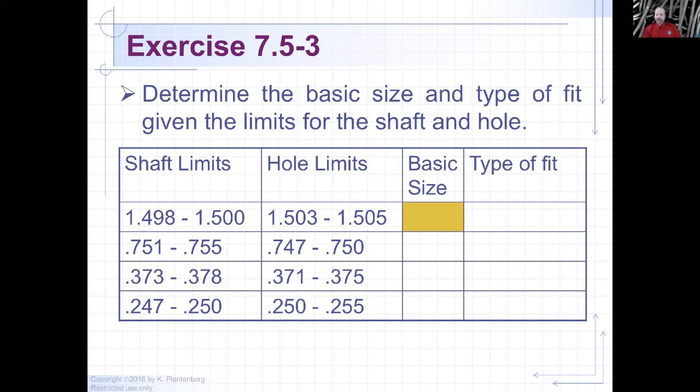We have shaft limits, from 1.498 to 1.500. And then we have hole limits, 1.503 to 1.505. So what do you think the basic size is? Any ideas? Yeah, 1.5. Okay.